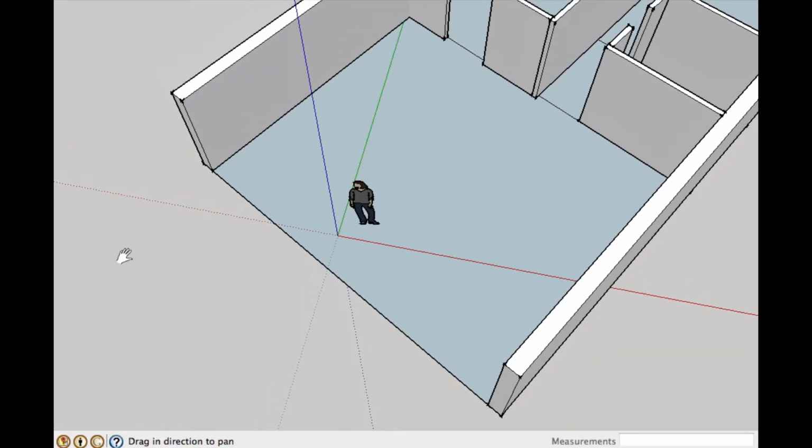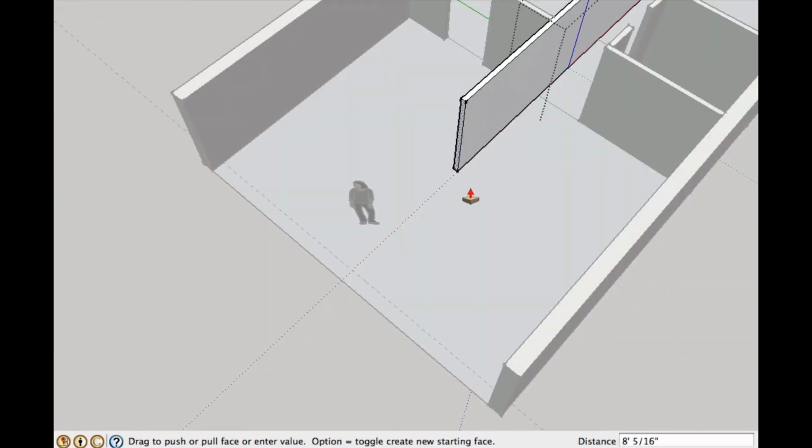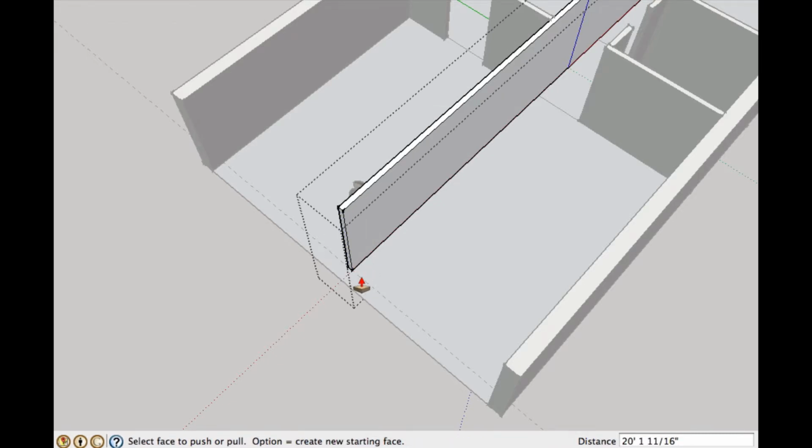So we could have set the exterior wall thickness ahead of time so that when we did those interior walls, we only went to the interior side of those exterior walls instead of all the way to the edge of the house. And we could have done this with the pointer tool and just come in 1 foot, right? And we could have done that on all the sides, and when we, for instance, extended this wall, we would go to that line instead of to the outer line. Okay.